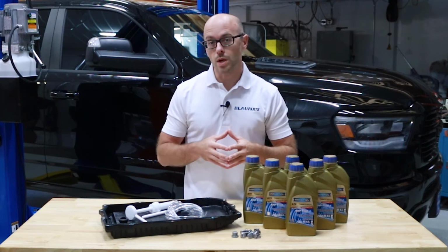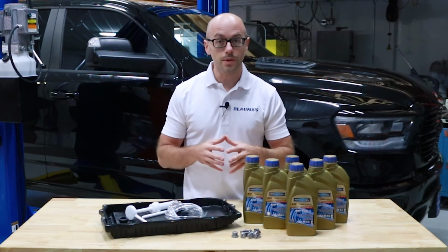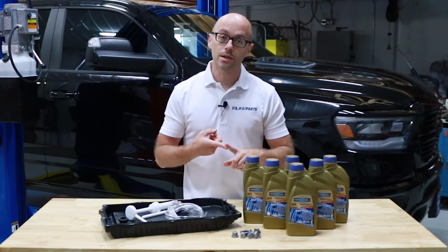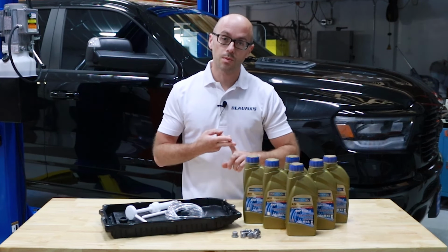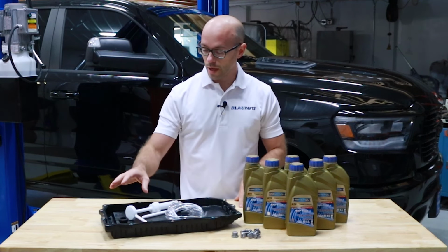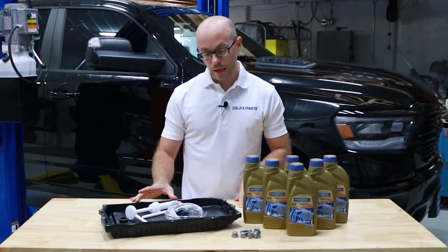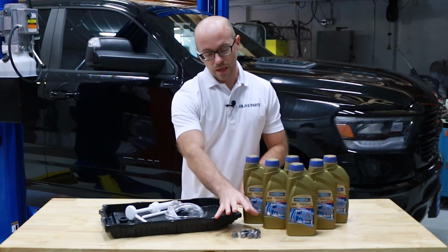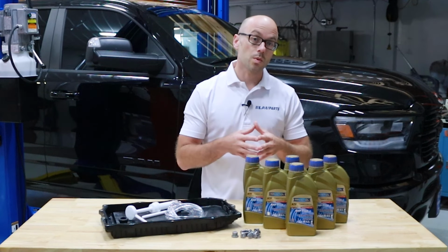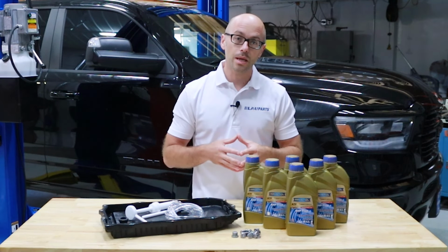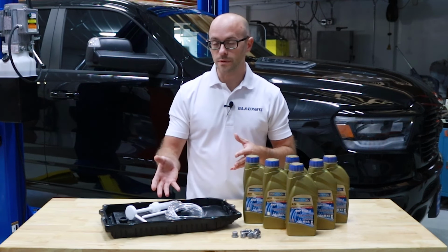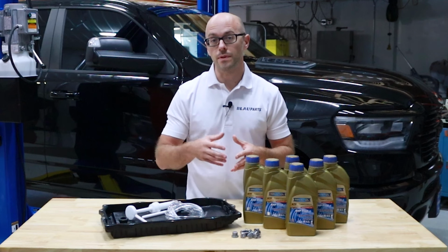For this demonstration, we're going to be using one of our Blau transmission fluid and filter change kits, which conveniently includes everything necessary for changing the transmission fluid and the transmission filter. We include the transmission pan, which has the incorporated filter and the incorporated pan gasket. Also, we have the necessary hardware and the appropriate amount of transmission fluid that's in accordance with the recommended ZF 8-speed automatic transmission fluid specifications. As well, we include a cost-effective fluid transfer pump for side filling the transmission.